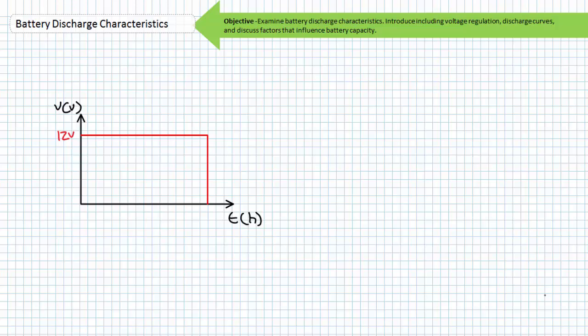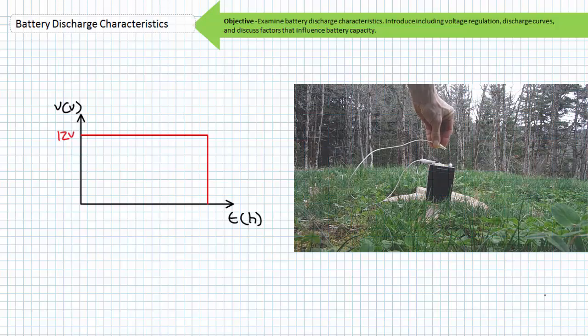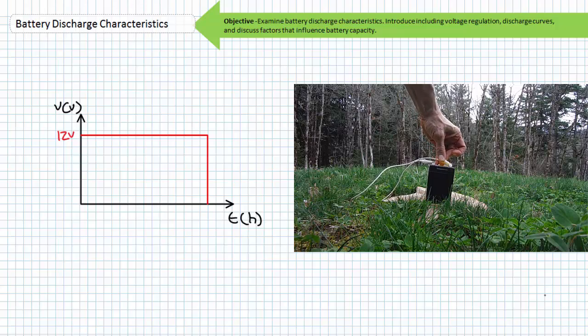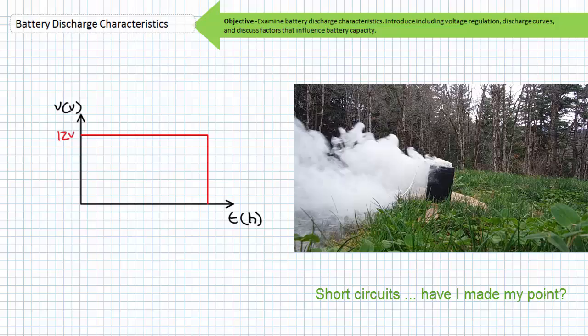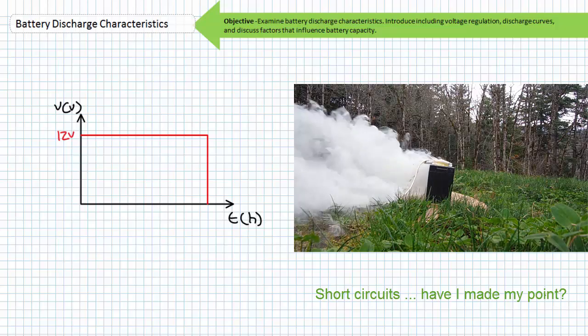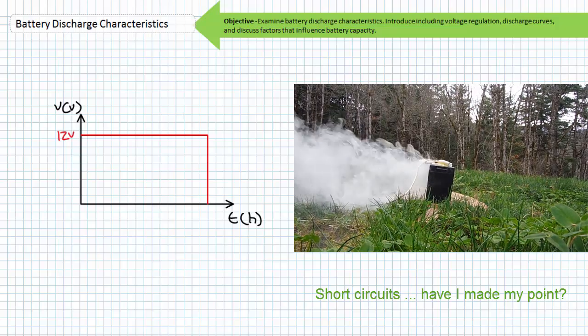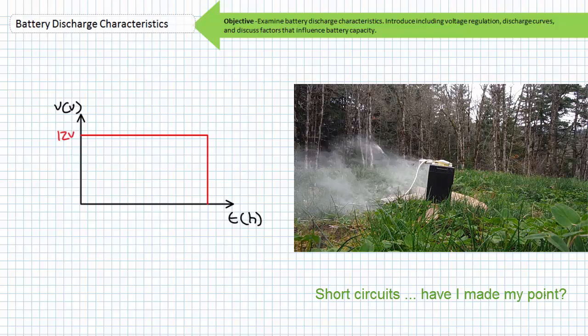Batteries can explode into a ball of white-hot fire or otherwise be damaged and rendered useless if you charge or discharge them incorrectly. A battery is an energy storage device and as such represents stored hazardous energy if it is not properly locked out and tagged out. A short circuit across the terminals of a battery, be it from a conductive tool or an errant wire that bridges the terminals, can produce a high current and damage the battery. Take necessary precautions when working around or with batteries.